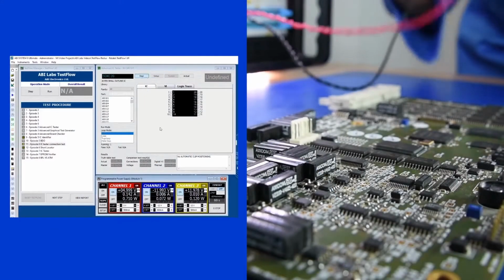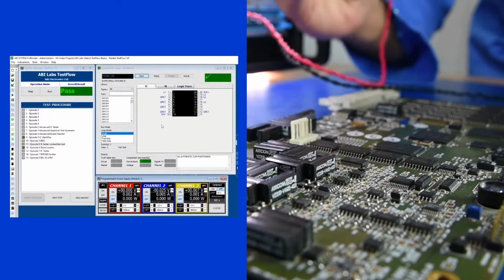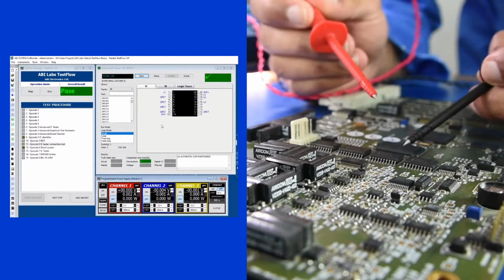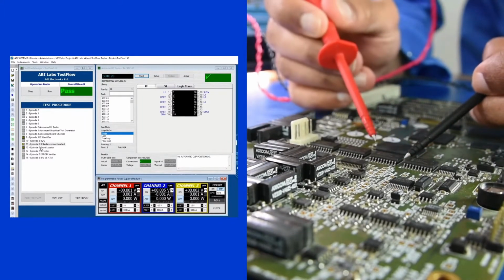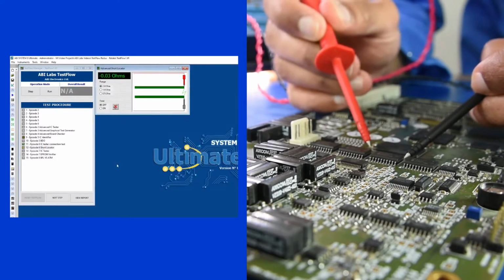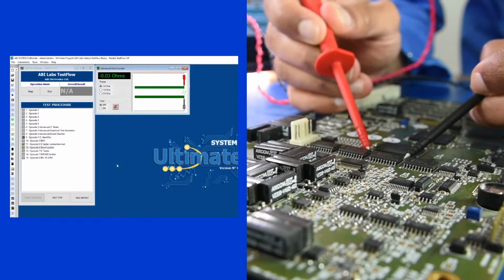And of course, there are many other applications. For example, we can use the power pins. Let's say we have an IC, and we need to identify where the VCC is, where the ground is. We can have one probe touching our power pins, the other probe going along all the pins of this IC, and then we can use that to identify where our ground and VCC are.